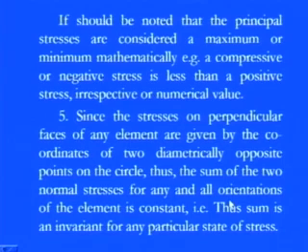It should be noted that the principal stresses are considered a maximum or minimum mathematically. Whether the stresses are negative or positive, they are just giving you the feeling about whether it's a tensile or a compressive nature.